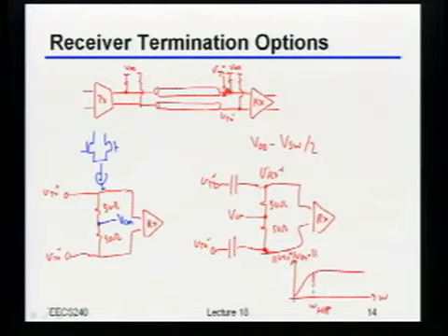If you have 64/66, the overhead is smaller, but the run length, meaning how many constant zeros or constant ones you can get, is larger. So then you'd have to push this even farther down. Great. Any other questions on this?